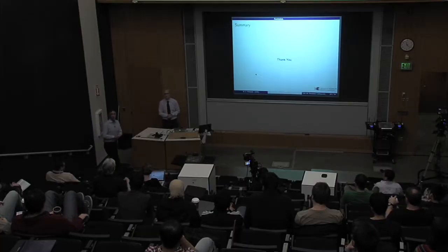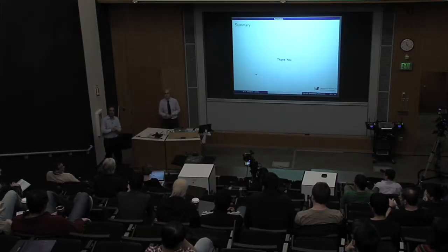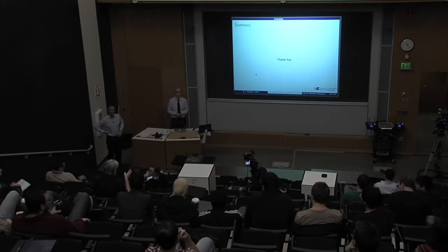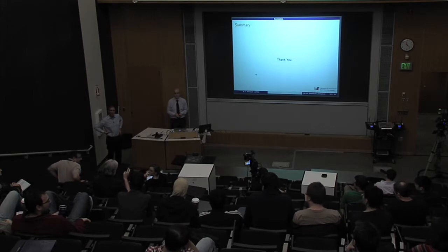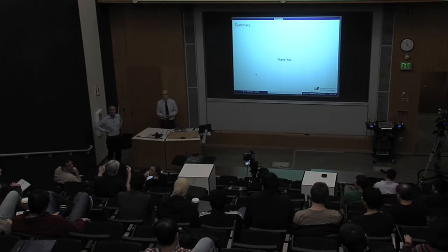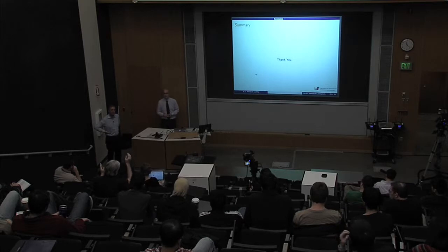Any questions for Brandon? Yeah. With the existing technology, if you have strings that are slightly mismatched in voltage, and you protect them by series diodes, now what happens to the low-performing strings? Are they just not participating at all because their diodes are back-biased, or do you pull the bus voltage down under load until they're all contributing something?